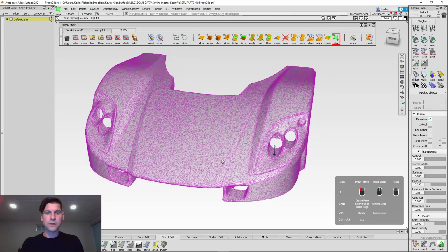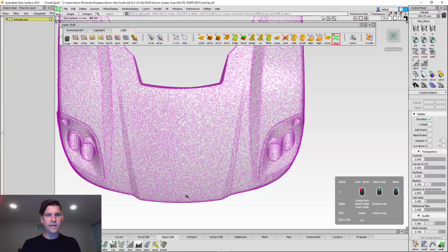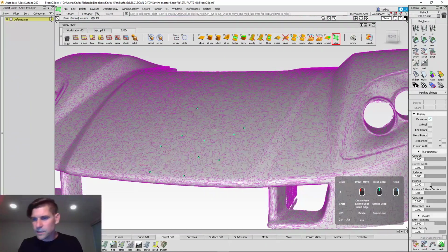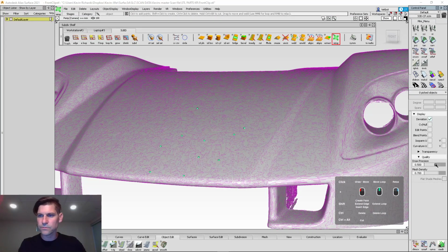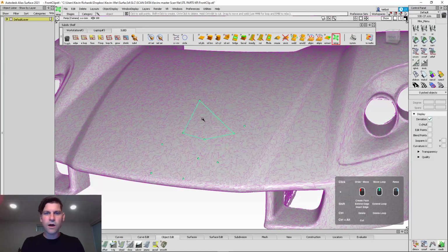So I have the mesh started. We'll just do half of the car, and instead of trying to match it along the center line, we'll take care of that later. First things first, I'm just going to place some points. And let's just get crazy here for a second, right? So here I've just got points. I think you can see those all over the screen. Let's turn down our mesh a little bit just so we can really see it. And if I hold down Shift, it automatically will try to connect those points to create a quad sub-D. Here they're kind of a mess, so I'm just going to undo those.